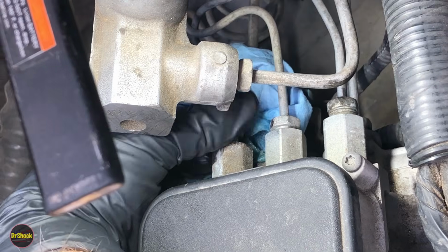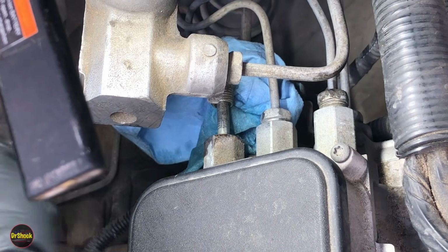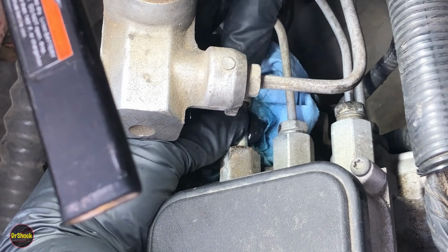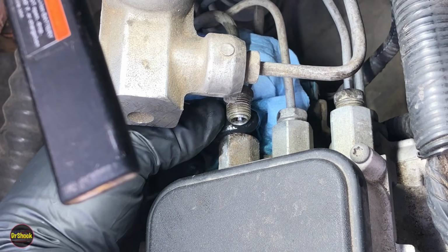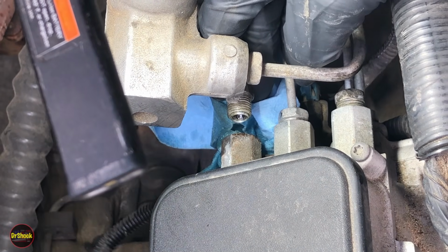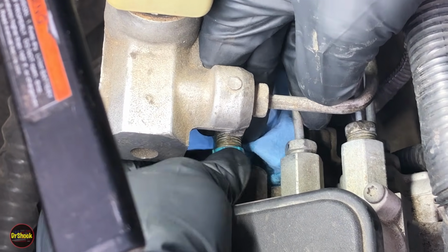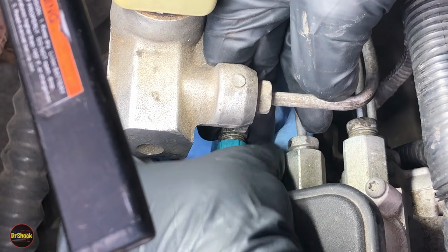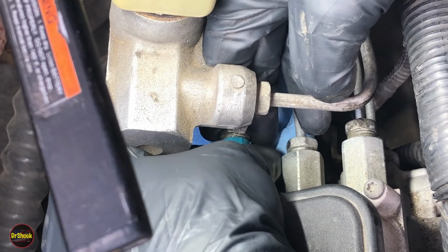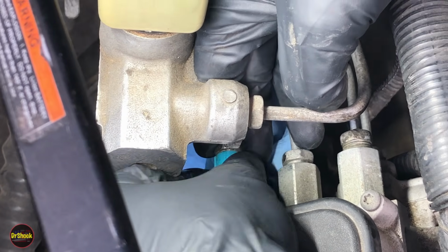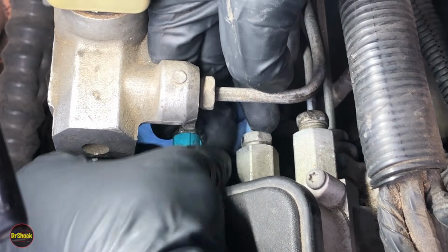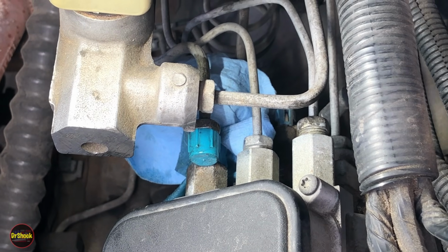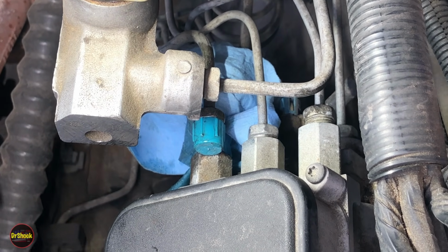I'm not going to show you all of these, but once you get this brake fitting off, you can slide it back a little bit. You can reach back and very gently pull the pipe out. Then to cut down on the fluid loss, get yourself some kind of a cap. If you don't have a cap, you can get a Ziploc bag and rubber band it around. That's the approach we're going to use with all 5 of these to cap them off. So we're going to keep on going. As soon as I get the last fifth one off, then we'll come back and continue removing.